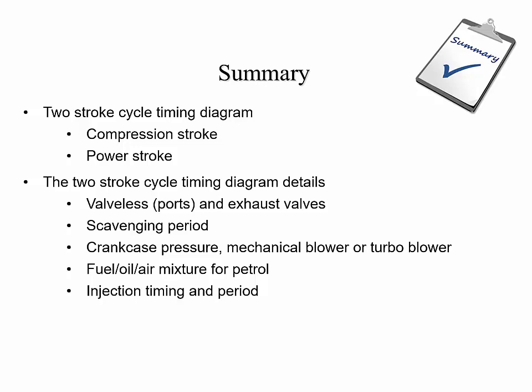And then we looked at injection timing and injection period. The thing to note is that injection timing can be variable, or it can be fixed injection timing, depending on the speed of rotation of the engine. If it's a constant speed engine, then you want fixed timing. If it's a variable speed engine, then it's desirable to have variable injection timing.